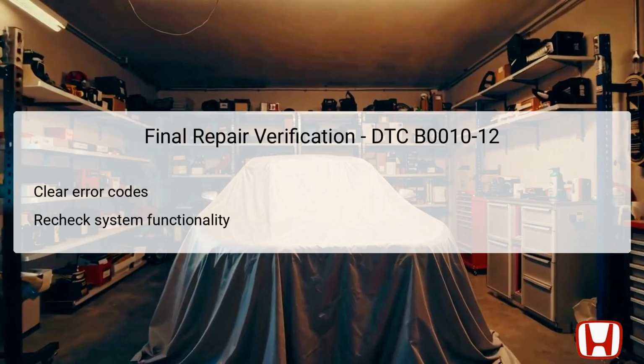After completing the necessary repairs related to DTC B0010-12, you'll want to verify that the system is operating correctly. Start by clearing any error codes stored in the SRS unit using a diagnostic scanner. After clearing, recheck the system by powering the vehicle back on and observe whether the airbag warning light remains off.